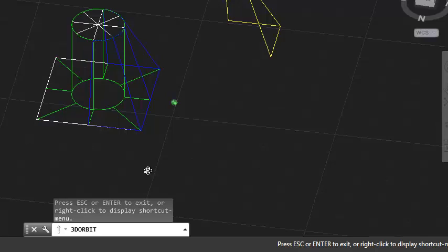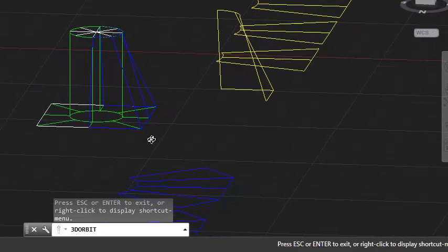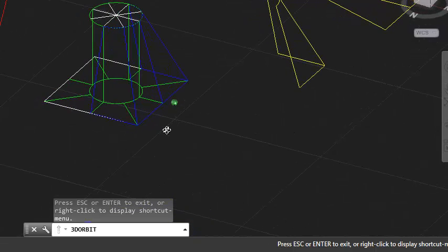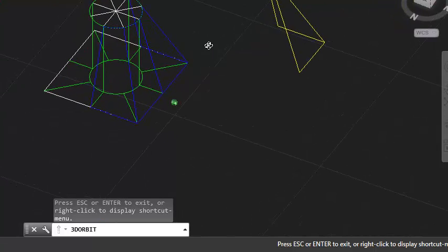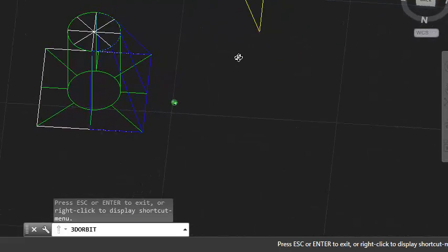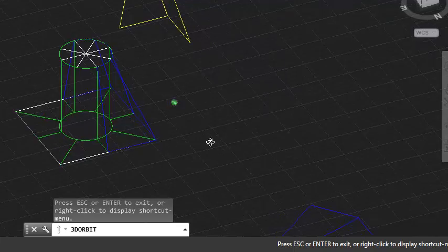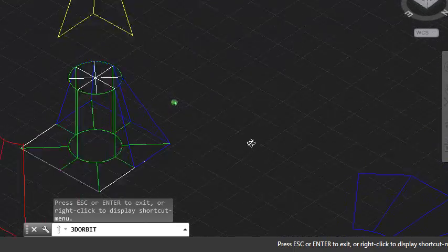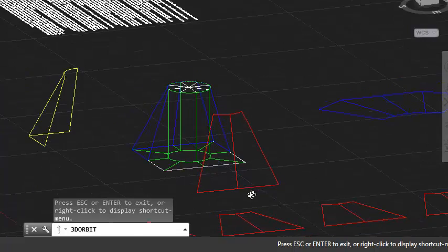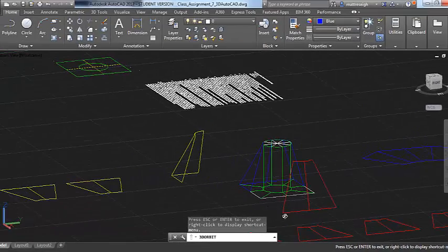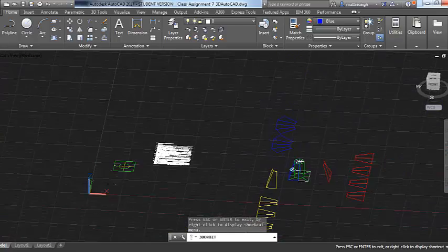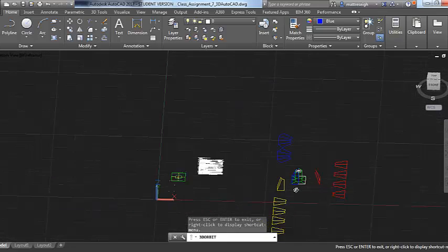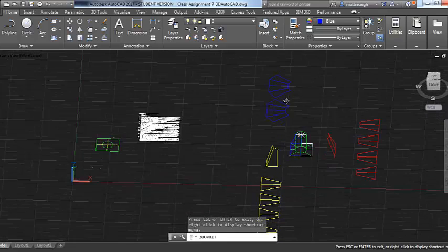But drafters do get progressively creative, and they do some interesting designs when it comes to unfolding a 3D model. But what we're going to do is just really common ways. I just wanted to show you those. So these really all just relate to weld seams and where I put my weld seams and how hard the pattern is to manipulate. But really it's the same pattern. It's just a quarter pattern, and whether or not I add some 90-degree bends to it and add on more sections of this and simplify the pattern. But really, the interesting thing to me is, from the red pattern that I like to start with, I can pretty much make any of these. I just split them in half and add them to the ends.